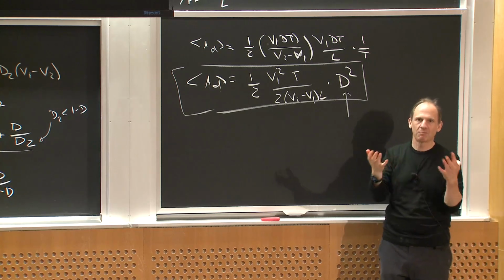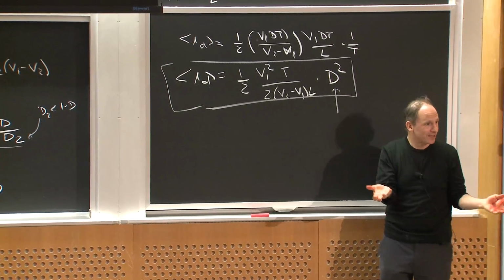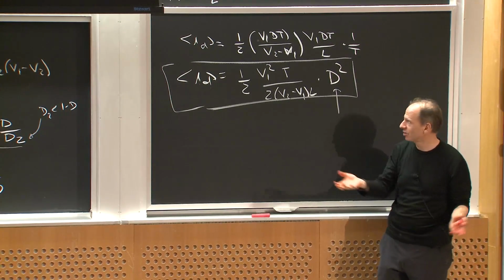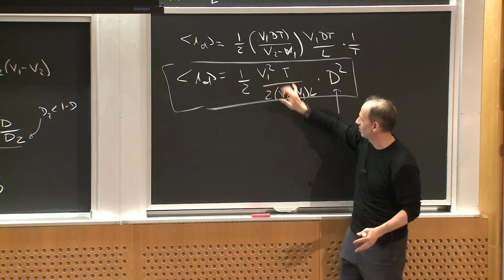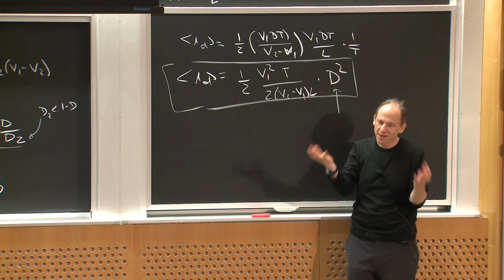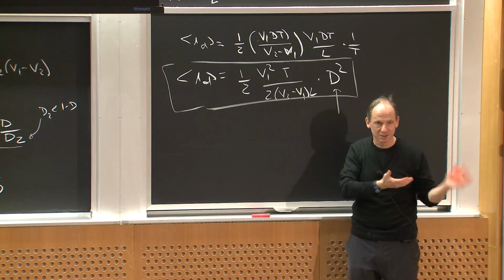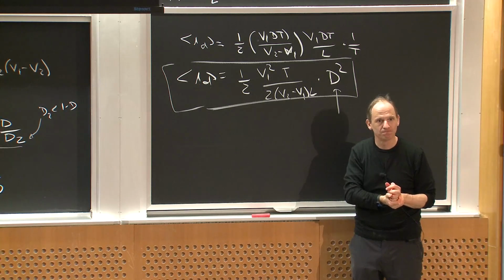Okay? So that's how I might model a DCM converter. It's more complicated in some sense than my continuous conduction mode converter because it's a function of all this junk. And my switching period and my inductor value and all that stuff matters where it didn't before. But I have to live with that because it's this more complicated operating mode.